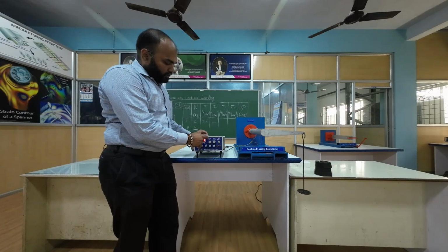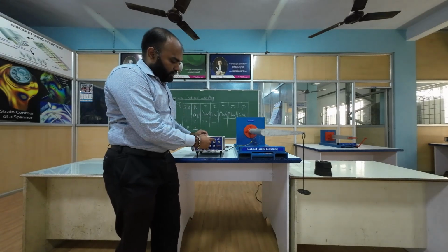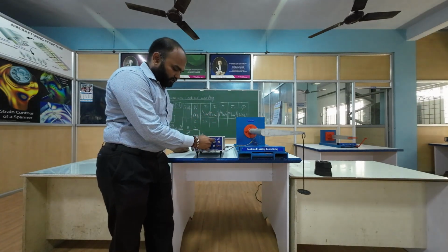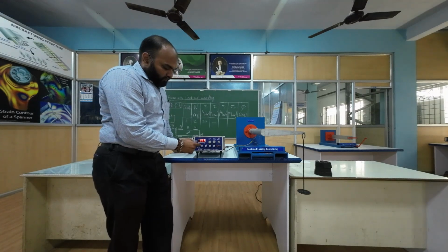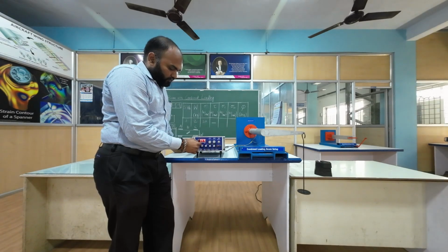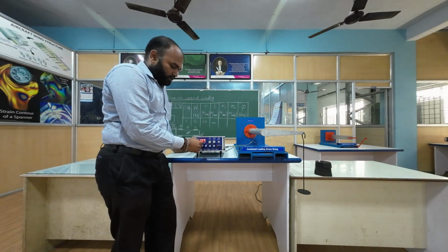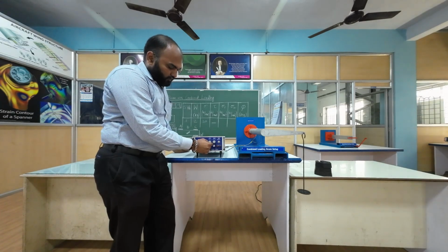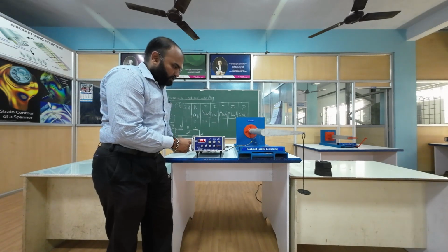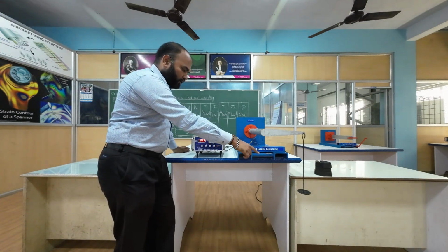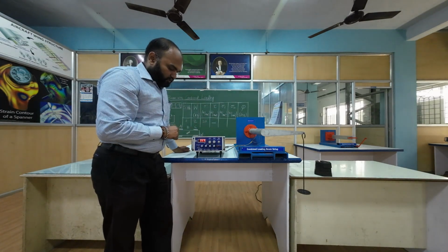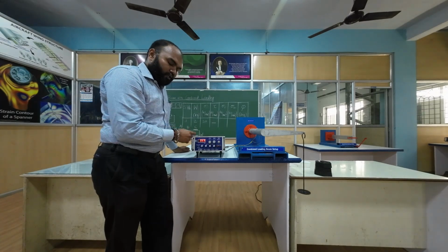This is the channel selector, and then you can select which bridge you want to use, whether it is a quarter bridge, half bridge or full bridge. Then we have the refinement levels, whether you refine in a coarse way or a very fine way. Coarse will be in terms of hundreds or thousands, and fine will be in very fine numerics. You can set your desired value before starting the experiments, then add the load in the hook, see the strain at the given points using the channel selector, and record the strain values.